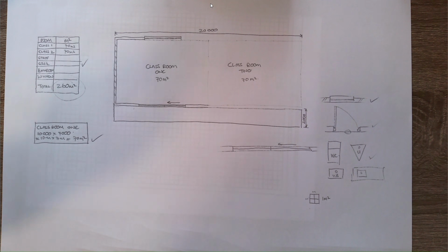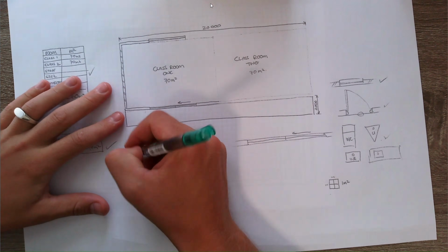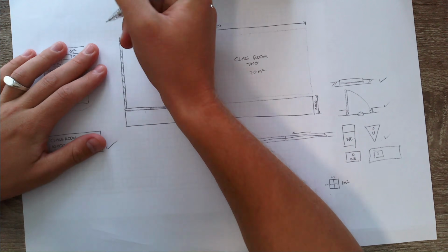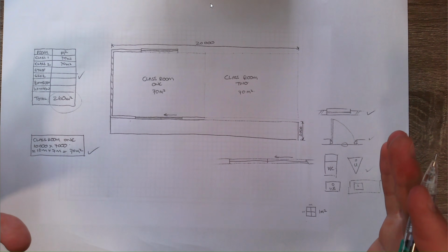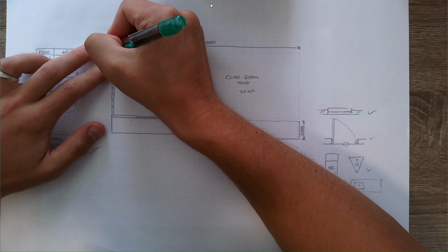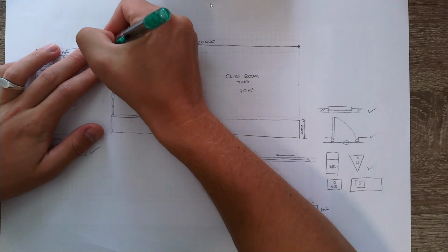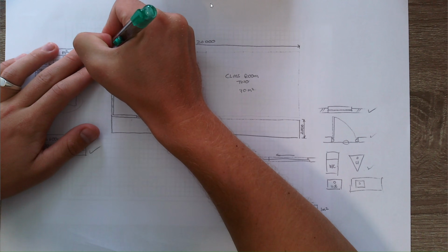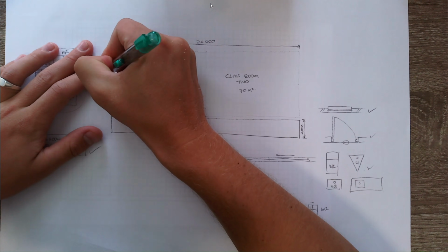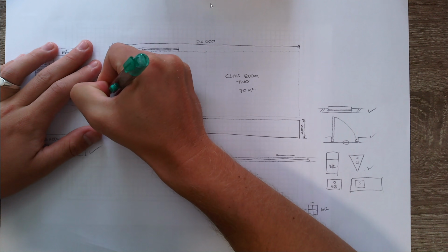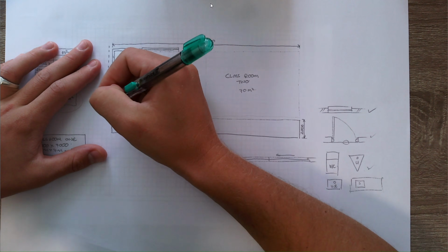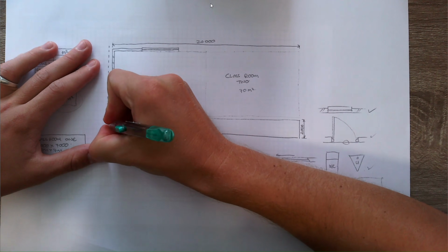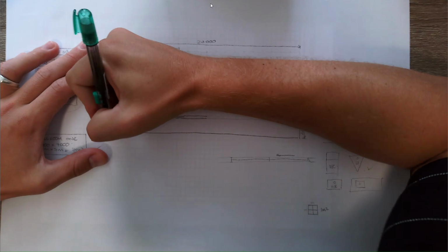Do not forget to show the roof detail. You're going to show the roof detail by adding dotted lines. And remember, you are going to have an overhang at the ends, so the dotted lines should go past the wall. So you're going to put the dotted lines in. This shows the detail of the roof.